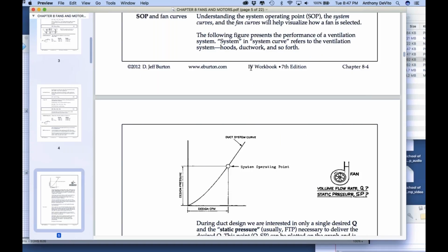I'm not actually going to design that tonight, right? Simple enough. Go out, the amount of ductwork you've got, the elbows, the stack, the length of the pipe, and so on and so forth. You do that exactly the same way we did the suction, except the numbers are positive now, right? So we're going to have a fan total pressure that we calculate based on the suction pressure and the discharge pressure of the fan. The discharge pressure we calculate based on how much ductwork and how many turns we have to go through to get the air out of the building.